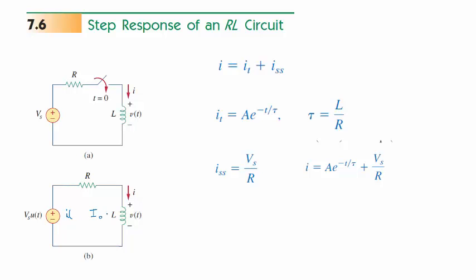So the current at the instant the switch is closed, which is the same as the instant the switch is opened, is this initial value of I0. So that's essentially at t equals 0. So we go over and we use this equation: I at 0 we know has to equal capital I0, the initial current, and we substitute that in.